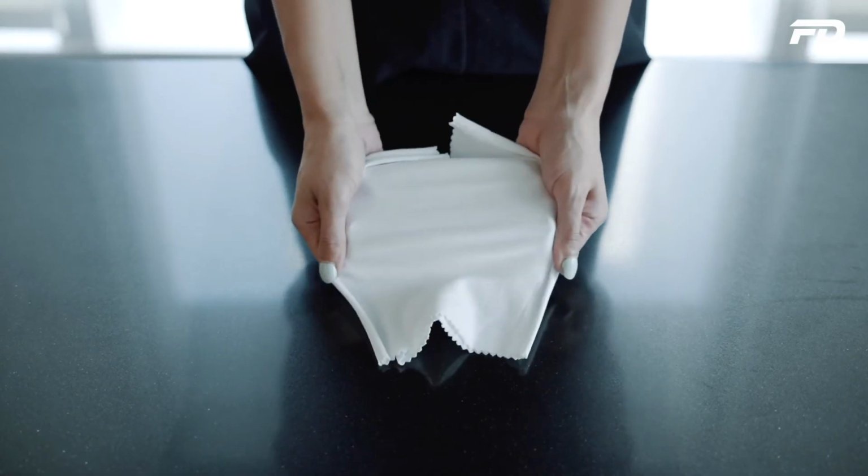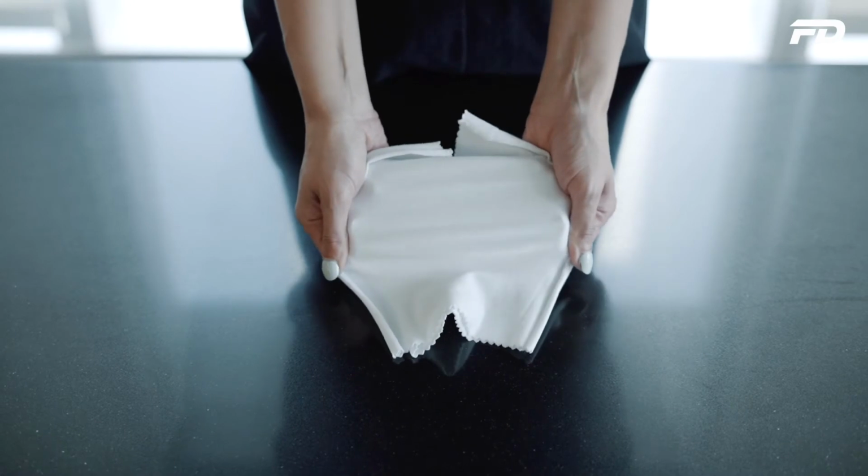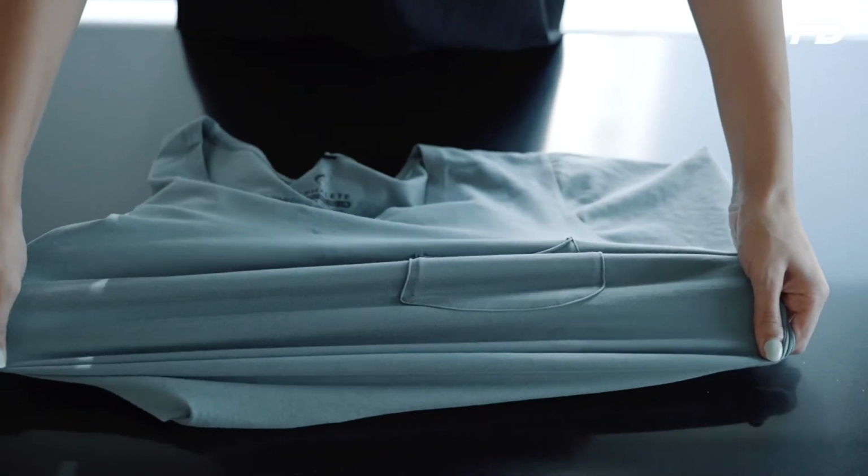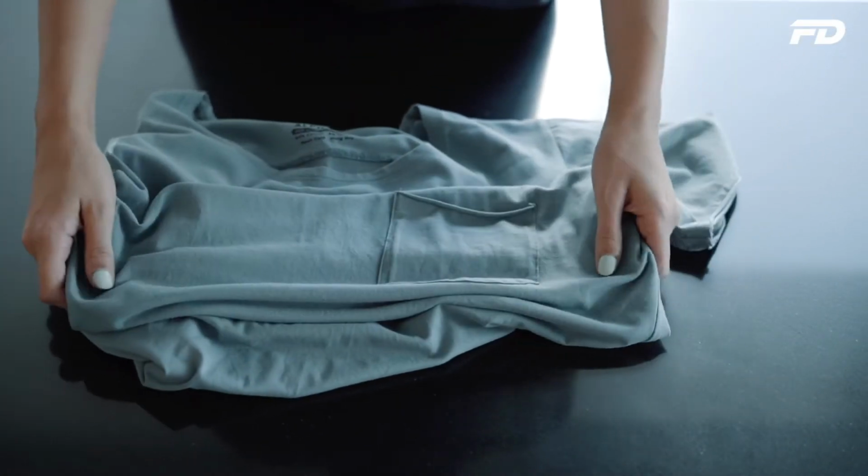We're using the 95 cotton here to give it a soft, non-allergenic touch and finish, and then we're using spandex because 100% cotton tends to be not as flexible, not as versatile, or not even as durable over time. Cotton tends to lose its shape when being stretched periodically and repeatedly over time, which can happen during multiple wears and washing. So adding that bit of spandex will allow it to stretch and still retain its shape.